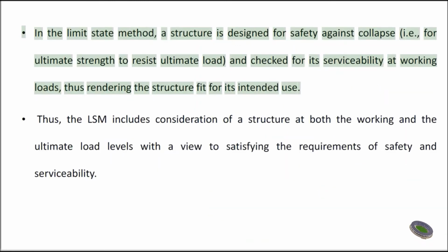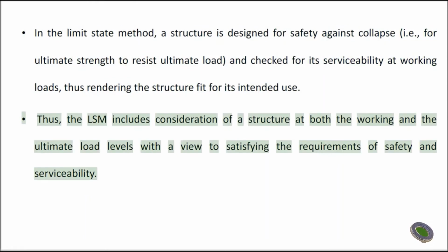In the limit state method, a structure is designed for safety against collapse, i.e., for ultimate strength to resist ultimate load, and checked for its serviceability at working loads, thus rendering the structure fit for its intended use. Thus, the LSM includes consideration of a structure at both the working and the ultimate load levels with a view to satisfying the requirements of safety and serviceability.